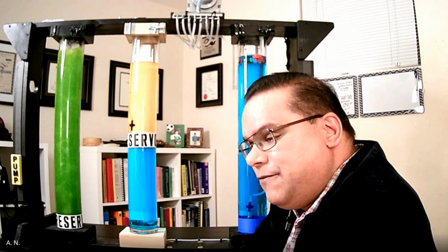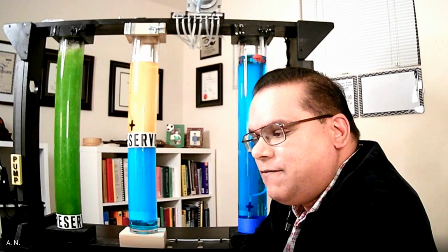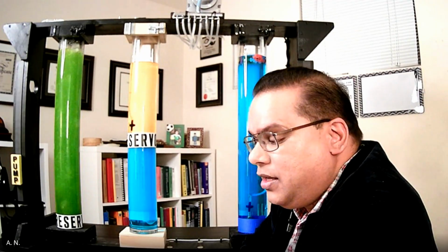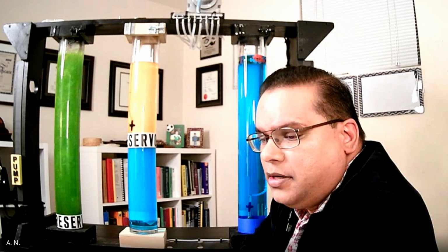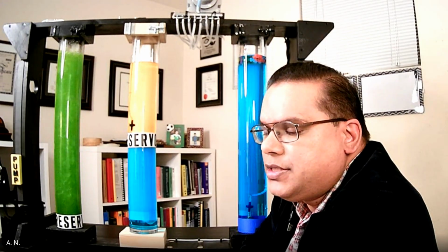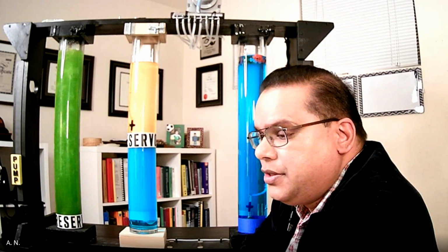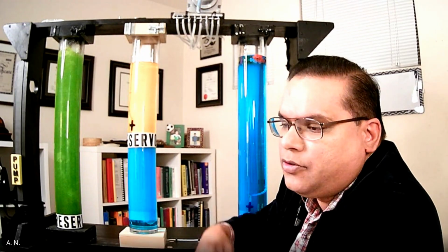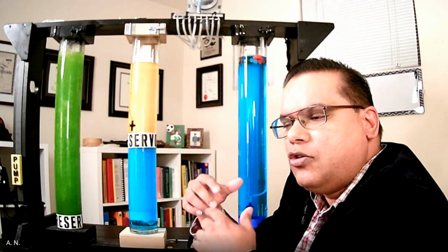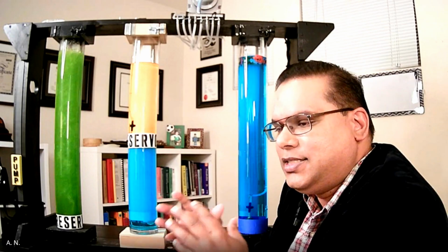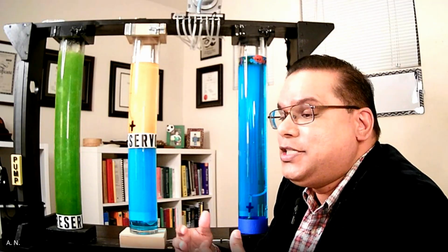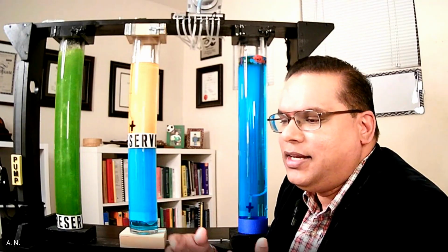So multiphase mixing and multiphase flow concepts are very important to your production optimization and to your artificial lift wells, and I dare say to your natural flowing wells as well. Because if you have very poor predictions in multiphase flow correlations, and your correlations are only tuned to pressure, you're not guaranteed to get anything else correct, right? So you still have the wrong velocities and the wrong trends, because pressure is just one global macroscopic variable that you can get the same pressure from changing anything. You can change holdup, you can change fluid properties, you can change viscosity, and you can even change a measured quantity such as diameter. And that's what's being done right now.